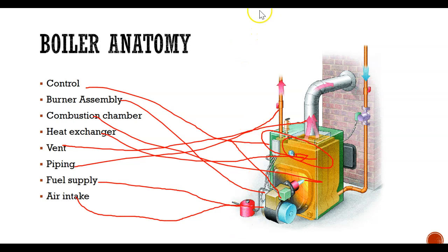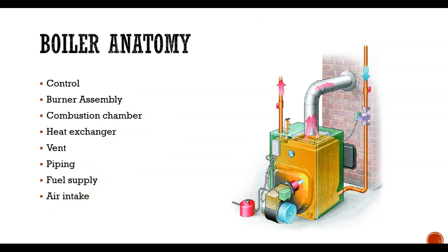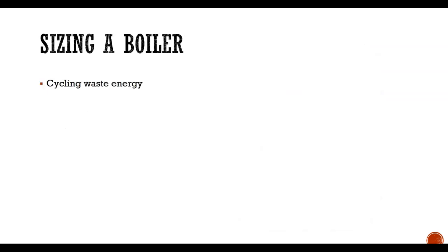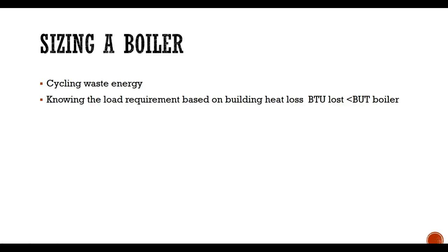Okay, that was good. All right, moving on. Sizing a boiler. It is very important to size the boiler, and you do that once you do the heat loss for each room. It does reduce the cycling, which wastes energy. And again, we did talk about oversizing a house and trying to open the windows or have it running without calculating the heat. That's not a good thing. If you do that throughout the season, you will lose a lot of heat and eventually it will affect your fuel bill.